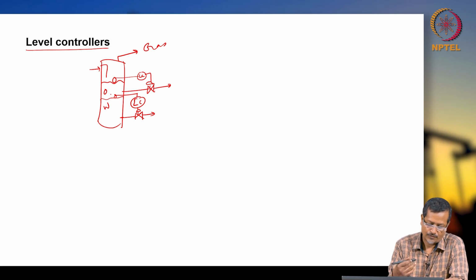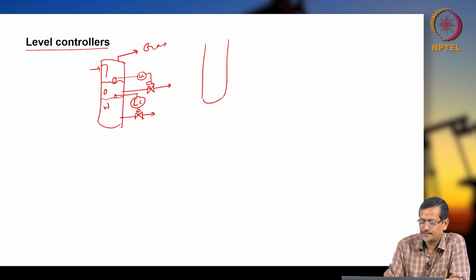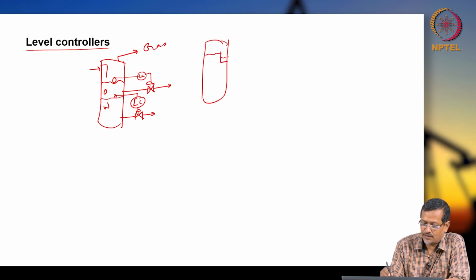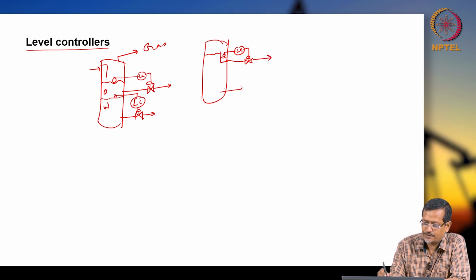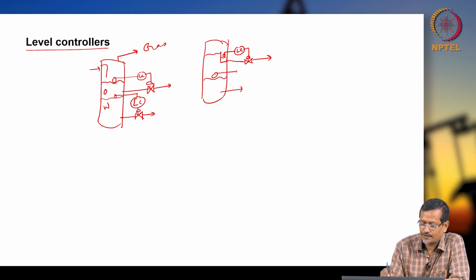Now, you have interface control with oil chamber. So, you create one oil chamber. Already we explained, but again this is oil you are collecting, but here you will have one level controller, and you are getting oil out. Water also you are getting with a level controller.